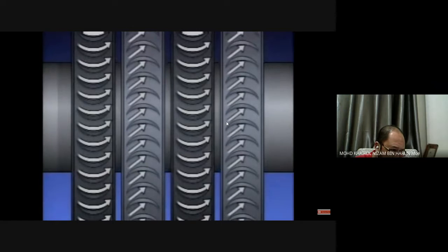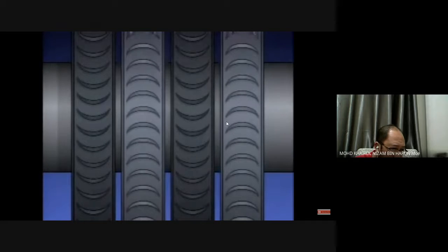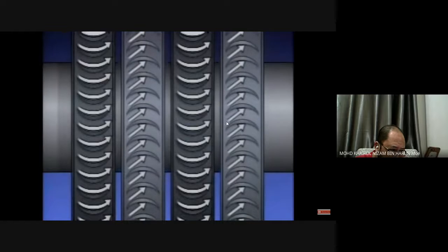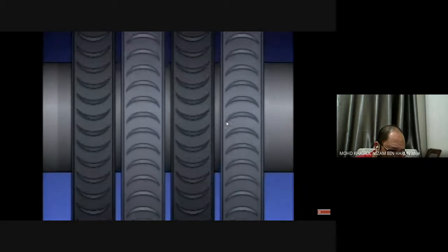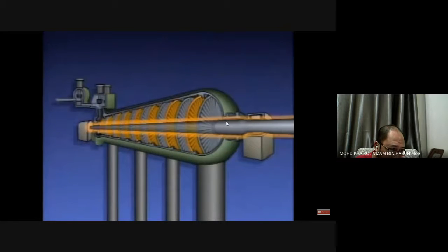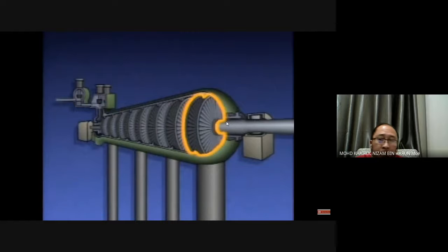Wheels, on the other hand, are moving parts. They are designed to turn as the steam flow passes through their rotating blades. The rotation of the wheels turns the shaft and the generator. Diaphragms are sealed where the shaft passes through them to minimize steam leaking through this opening and bypassing the diaphragms. Typically, the pairing of one diaphragm and one wheel is called a stage.